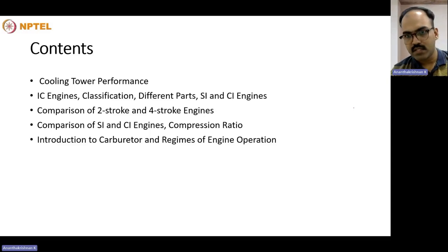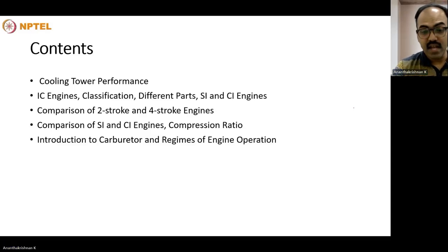The wet bulb temperature of air is a psychrometric parameter that tells how much water the incoming air can take before it gets saturated in an adiabatic process.